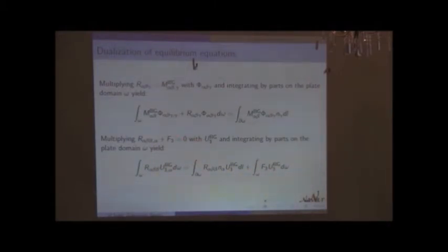This is the divergence of the shear force, and you just multiply with what will be the out-of-plane displacement as the Lagrange multiplier of this equilibrium equation. This is rather classical. But of course, with this third order tensorial equation, I need to introduce a third order tensor Lagrange multiplier. And this will be our generalized rotation.